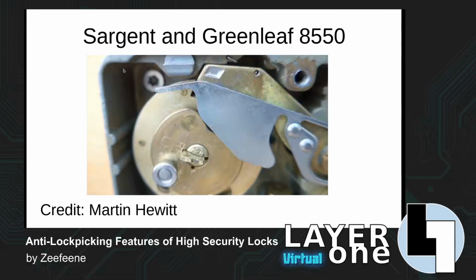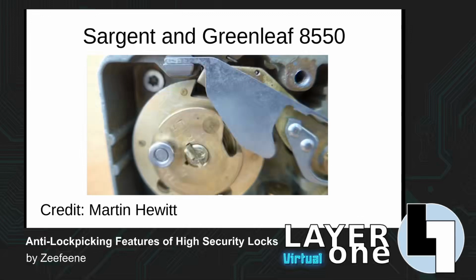And the thing that's curious about this is, in this particular position, the lever is held up by this spring and is not touching the wheels. But as we turn the drive cam, this silver portion will make contact against this slope, and it will push this silver portion up over this little ledge, and it kind of clicks in above this ledge, and it's held there.